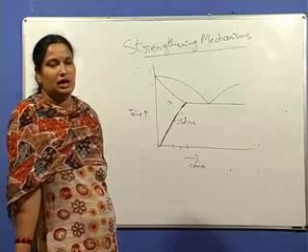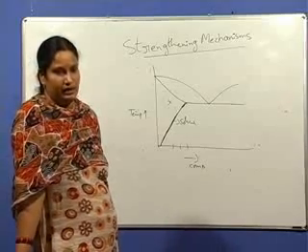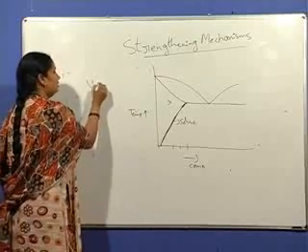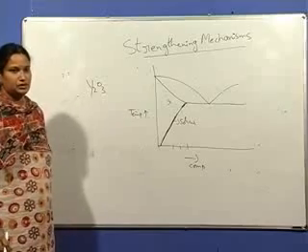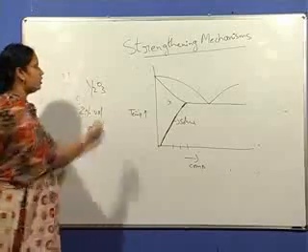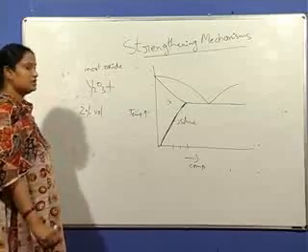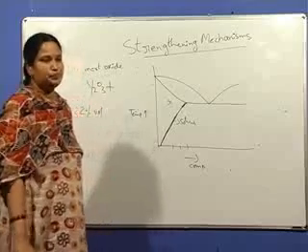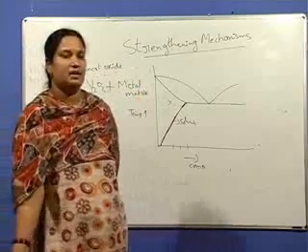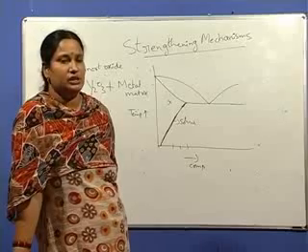Whereas in the case of dispersion hardening, it is also known as mechanical alloying, because metal matrix powders and inert oxide particles like yttria (Y2O3), thoria, and alumina are used. So these are the inert oxide particles. The volume is about 2%. Inert oxide particles, constituting about 2% volume, are mixed with metal matrix powders, and they are compacted and consolidated by powder metallurgical techniques or powder metallurgical routes.